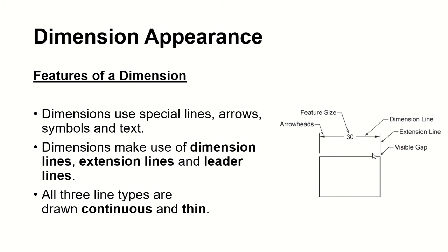All these lines, your dimension lines, your extension lines, and your leader lines, you draw them continuous and thin. Of course, they also have their own specific thickness.